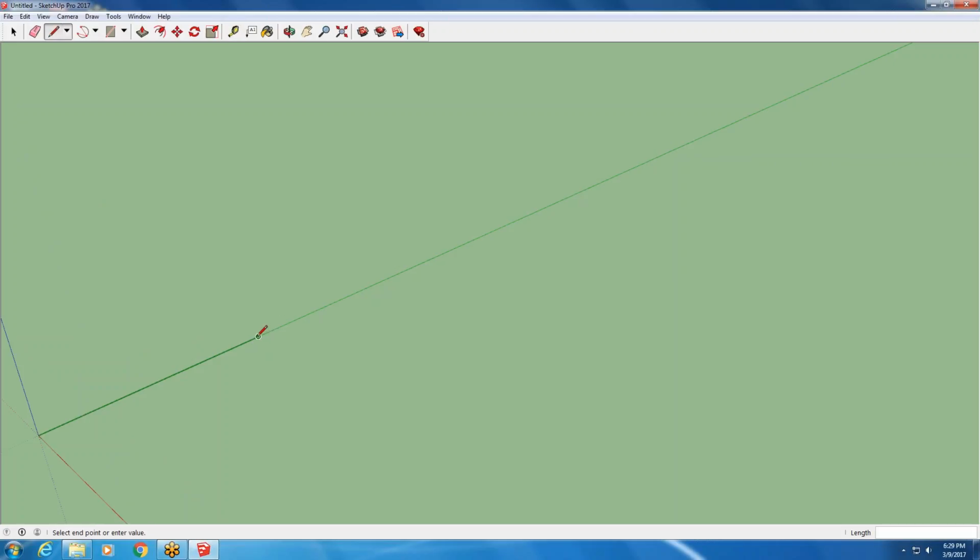So if I have a wall, I'll need some thickness to it, and I need to stay on the red axis to know that I'm on the same plane as that point that was created by going back in the green space. So I'm going to come over 6 inches. And then I could draw a line by clicking on that endpoint, and it wants to match up, like show me a node that is directly across from the first point. And then I have to click on that endpoint again and connect the other one to finish out the base of my wall.